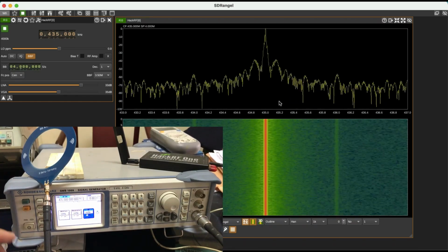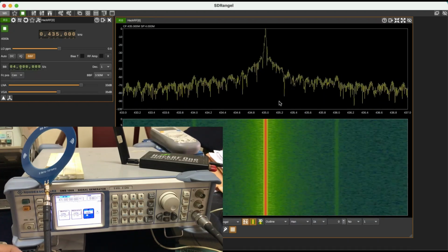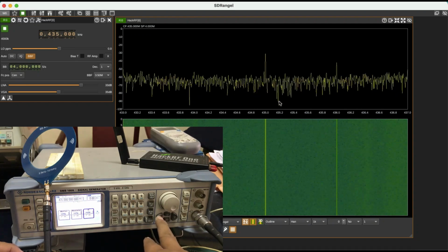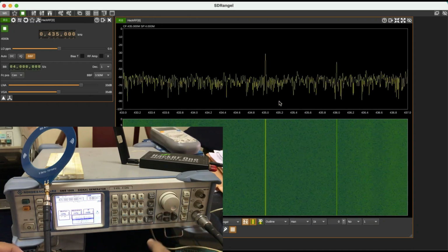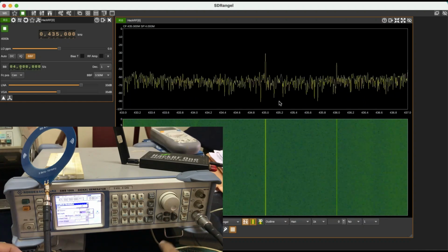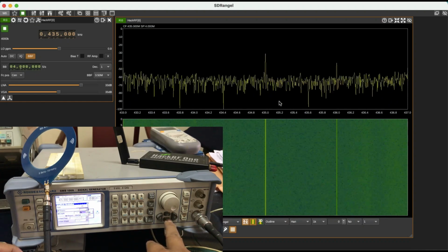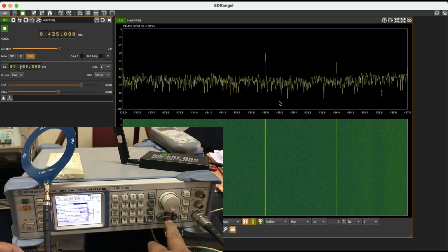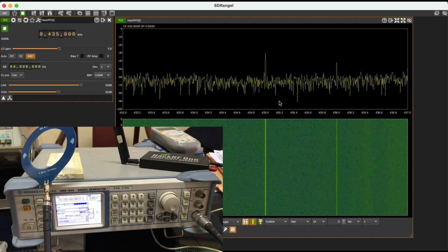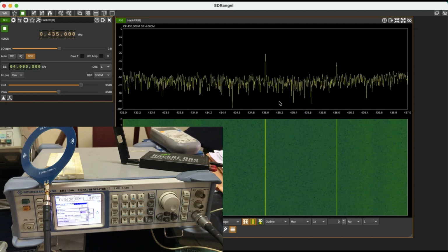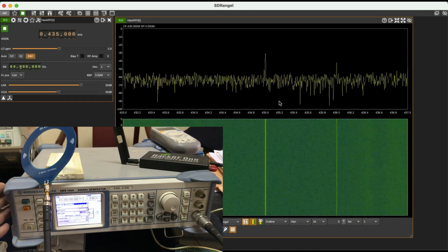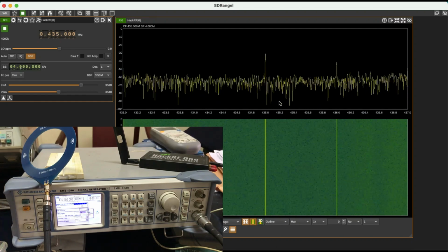All right. The next step I need to do, I can do some modulation. I can turn off my RF. I can go to my modulation box, click on it. Let's do amplitude modulation first. Once you go to this amplitude modulation, I can select the depth. I'm using an AM source, which is an internal source. It's going to generate a frequency from 20 kilohertz. You can have a frequency from 20 kilohertz, which is going to be a baseband signal or information signal, all the way up to 1 megahertz. That's the range of this internal generator.